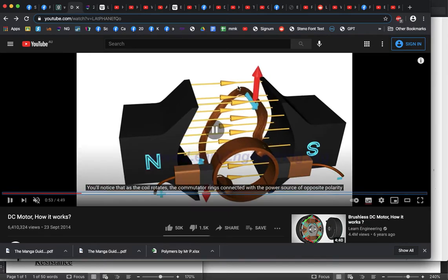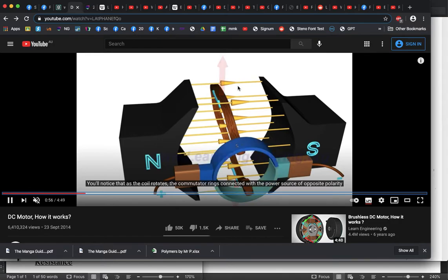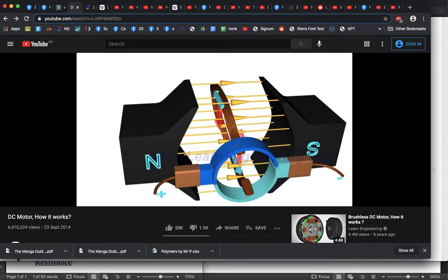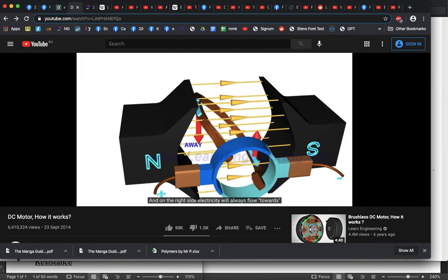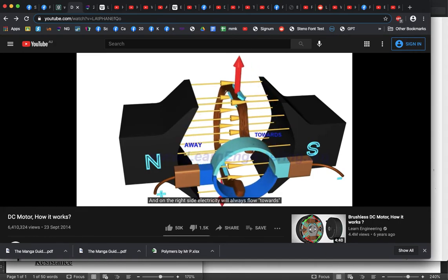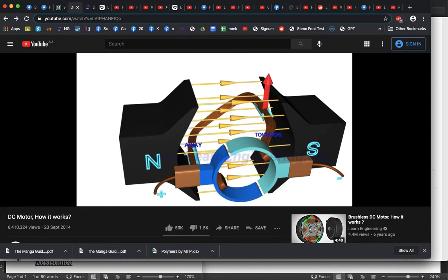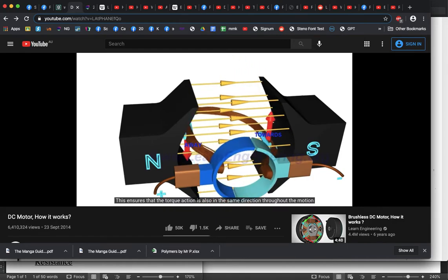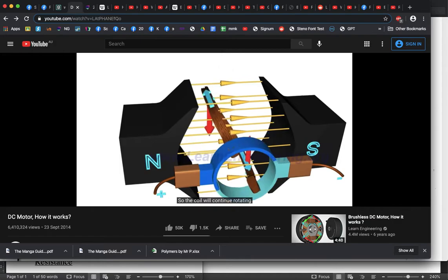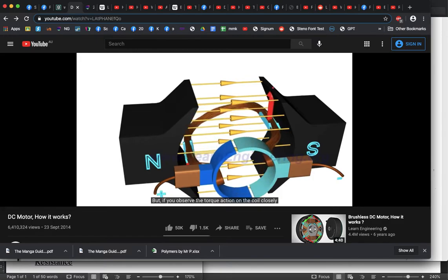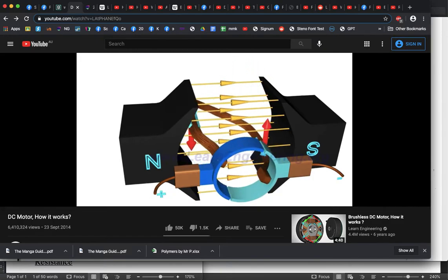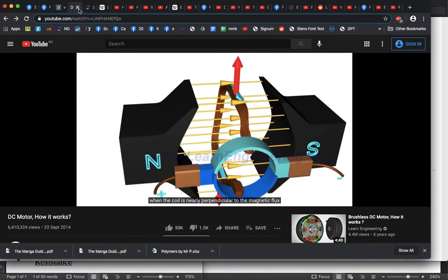This is now the second time I've done this video, so anyway, it's going down. I was right. What's amazing though is that as it gets halfway, the arrow is suddenly going to change direction for no good reason. The reason that it changes direction is because there's a split in the ring. You ready? Watching? It splits. Now, that's obviously more difficult than what we were doing with our homemade coil. How we achieve that is by just removing the plastic coating from one side. What happens is that only half the coil is going to generate movement, and the other half of the rotation is just going to rely on momentum to keep it going. So hopefully that makes sense.